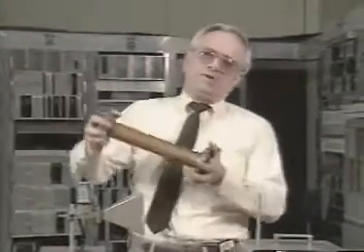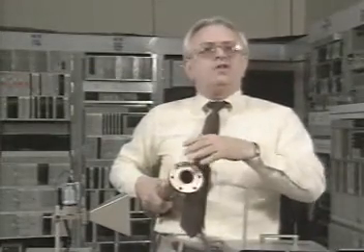This big beast would be another piece of waveguide. Round as opposed to rectangular, would operate at highly different frequencies, very heavy. You wouldn't want to do this very far. There still is loss in waveguide, even though the signal transmits up through the middle. As it bounces, as it travels, it loses some power. And all the power is down at the transmitter, not up at the antenna.